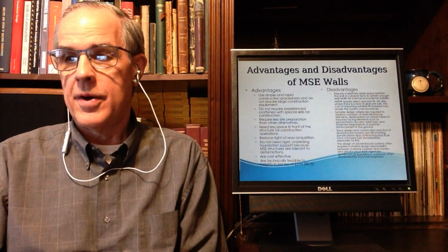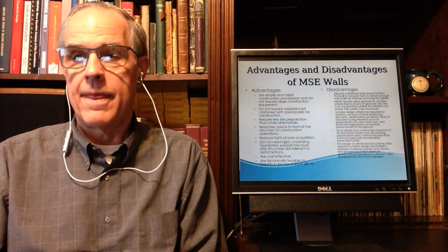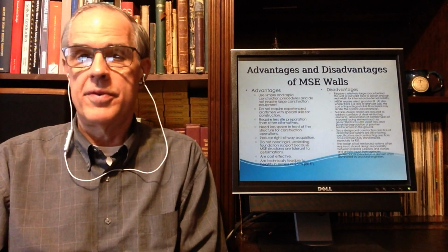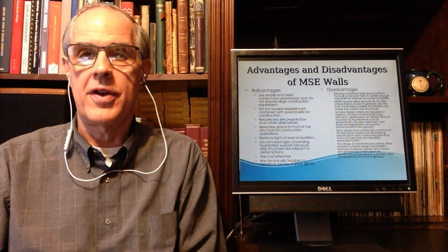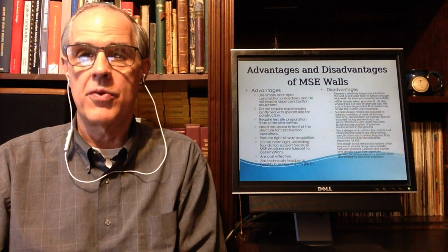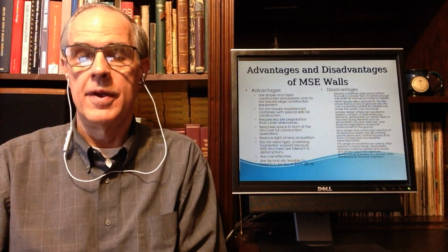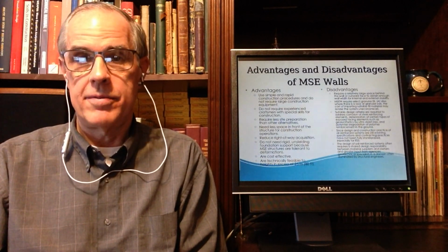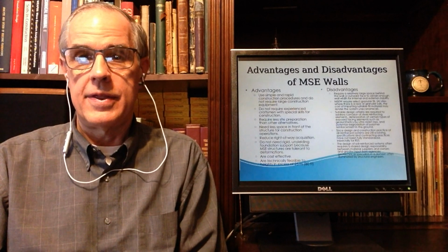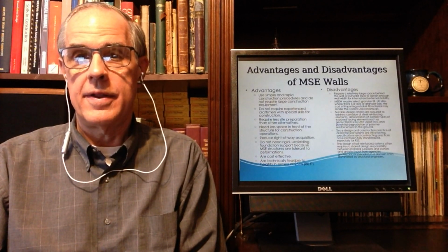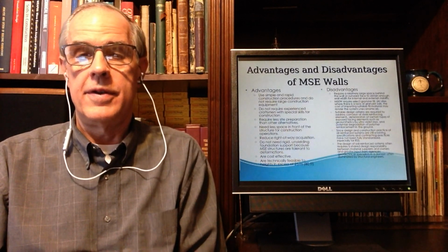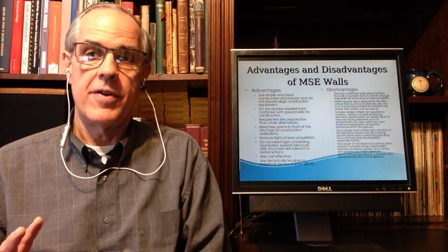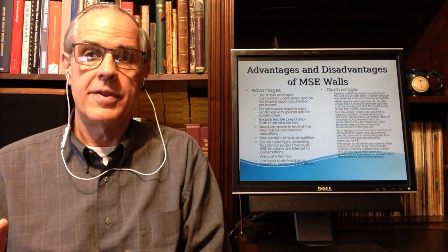Disadvantages. The biggest disadvantage is also its biggest advantage. MSE requires granular backfill. Sometimes that backfill can be difficult to obtain, and that can be a very difficult kind of thing.